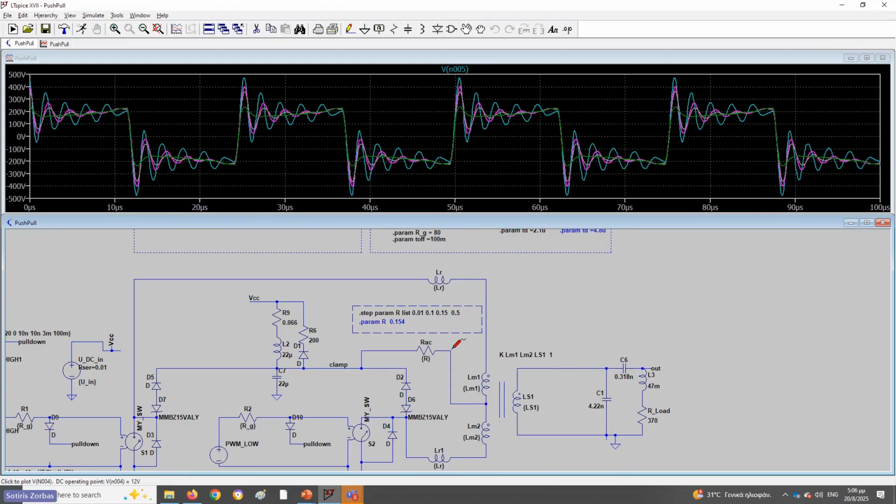Why do we call it RAC and not R total is a good question, but for clarity, this is going to be the copper losses of the entire transformer. But the point, the webinar is about how can we know this value before we even design the transformer, right? Maybe you're going to produce a very good design with minimal losses. So this RAC is going to be minimum.